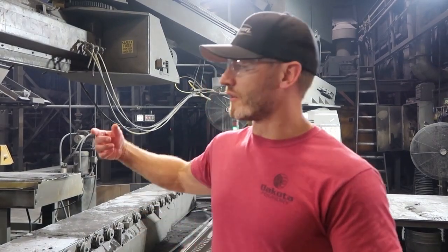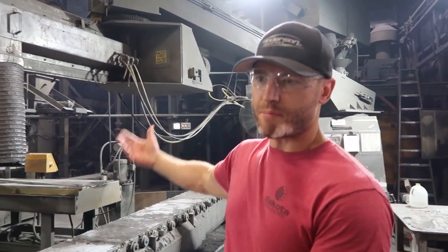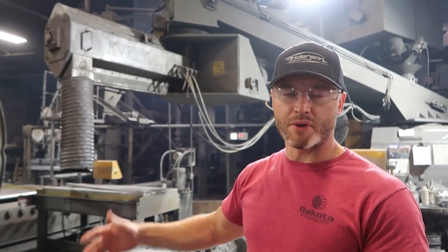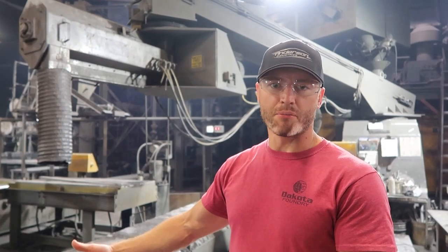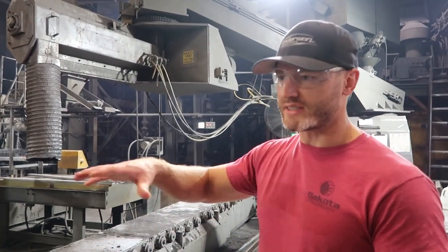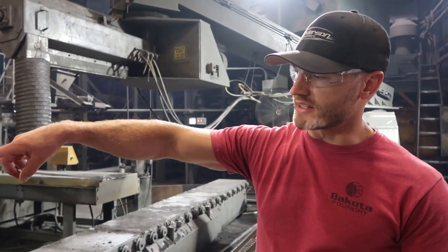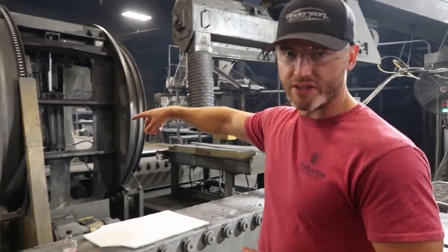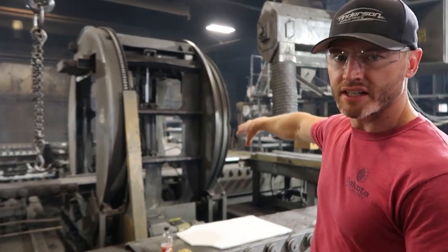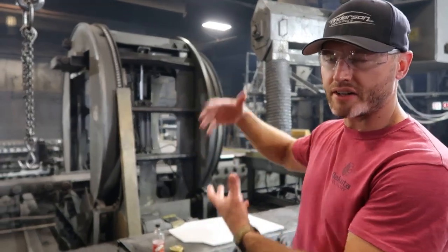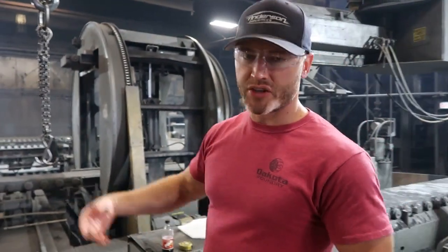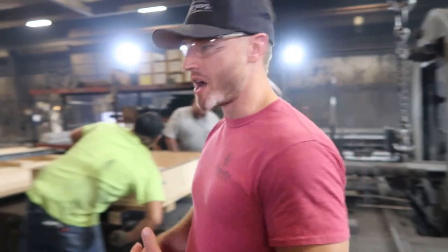And so this rollover system is designed, we primarily run in our own boxes, or we have insert boards where a pattern or an insert will be put into one of our production boxes. And so the boards get mounted, they run in this system. It's an automated rollover system where the pattern goes in and it rolls over, and the pattern and mold are separated. And here you can see an example of one of our production boxes.